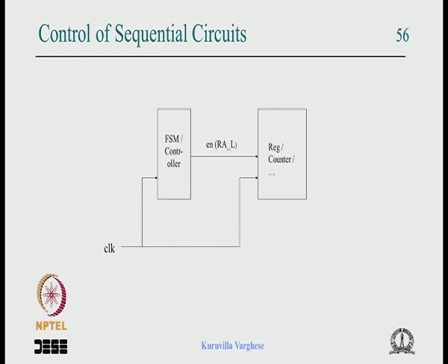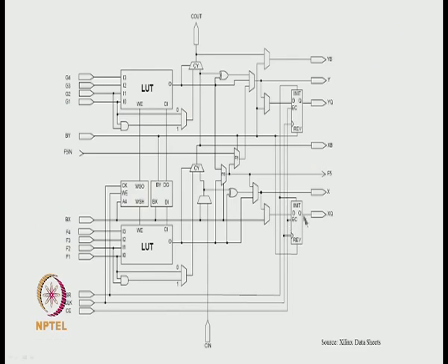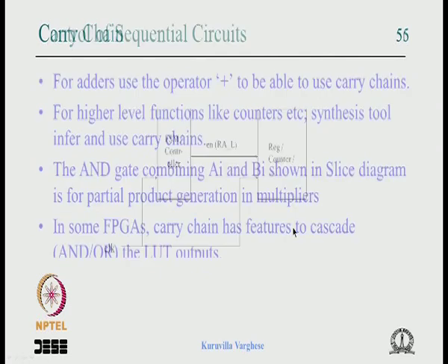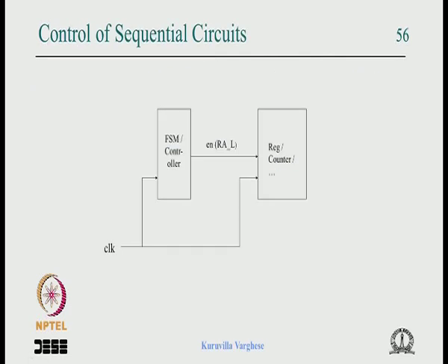So let us come to the flip flop now. I want to talk about this EC, or it's called enable clock. When we discussed our initial case study of the CPU, we said the controller will control the data path. Many times it will enable a register or a counter or things like that.